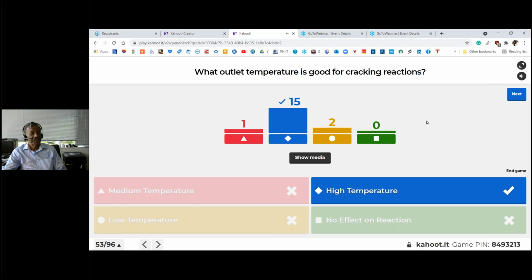High temperature, because it's an endothermic reaction. Endothermic means it requires heat. So as we increase the heat input, a higher temperature, we will have more reaction going towards the right, favoring the formation of more products. Generally, it's the tube metallurgy which limits us on the temperature. We would like to go even higher on the temperature, but the tube metallurgy limits us. But high temperature favors more ethylene.